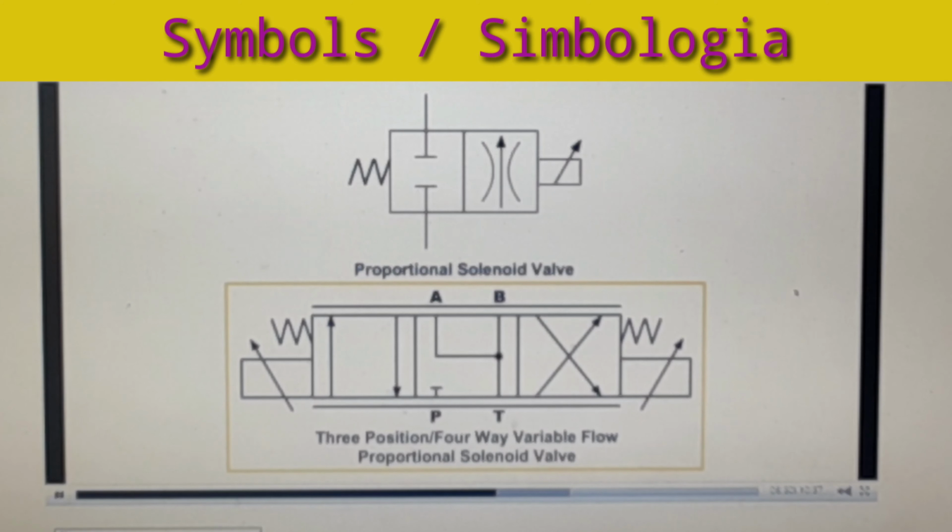This 3-position, 4-way valve is both directional and proportional to control the speed and direction of the function with one component. The lines parallel to the valve represent pressure compensation, so the amperage to flow rating is not affected by pressure or viscosity. It is shown as proportional with the diagonal arrows through the solenoids.